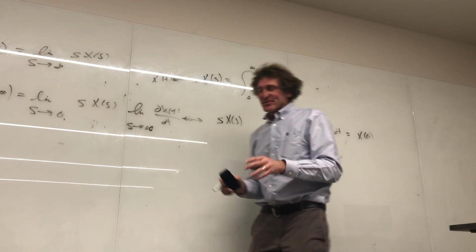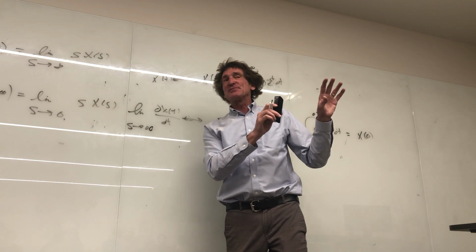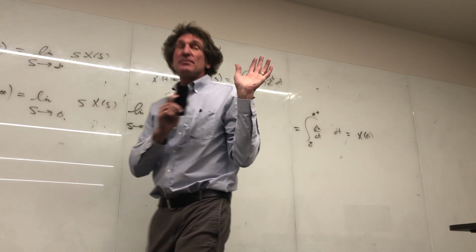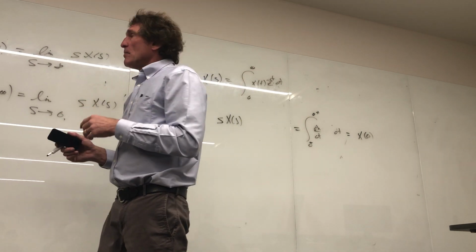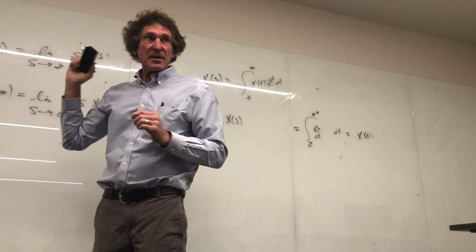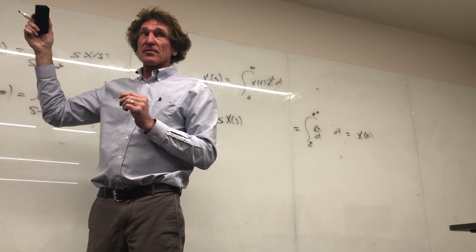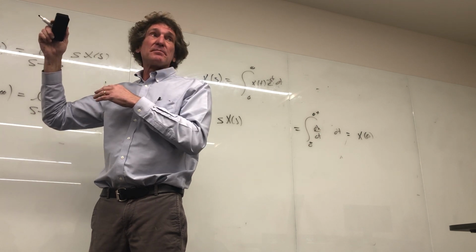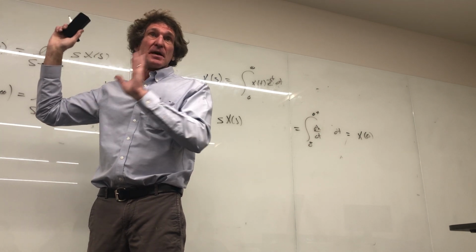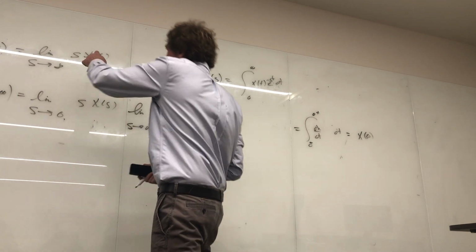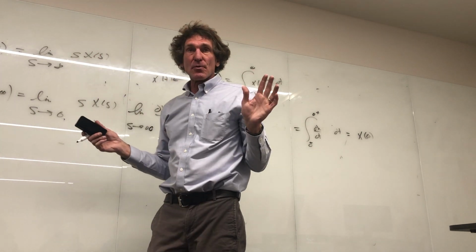Now, you can spend time with this after class. I don't spend much time on this because, frankly, I never use that. Only time I ever use this, and I'll tell you the real trick, I always look at the highest power of s in the numerator versus the denominator. If the numerator is greater than or equal to the denominator, I've got to show you some tricks in this. I do division, because that won't be a stable solution, and I'll show you how to deal with this in a bit. But for now, these two things are the only things that are important to know.